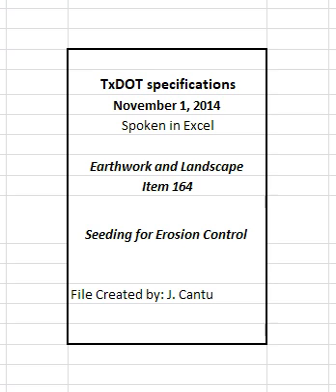2.5 Tacking methods. Use a tacking agent applied in accordance with the manufacturer's recommendations or a crimping method on all straw or hay mulch operations. Use tacking agents as approved or as specified on the plans.